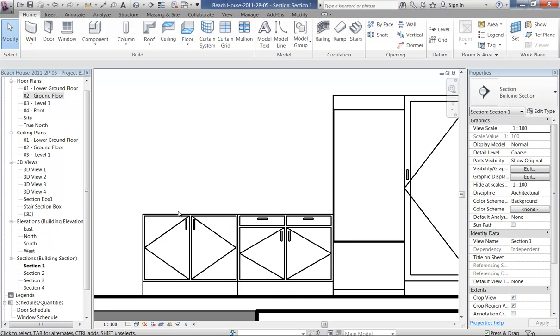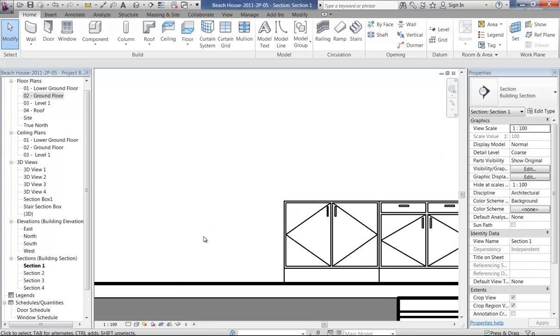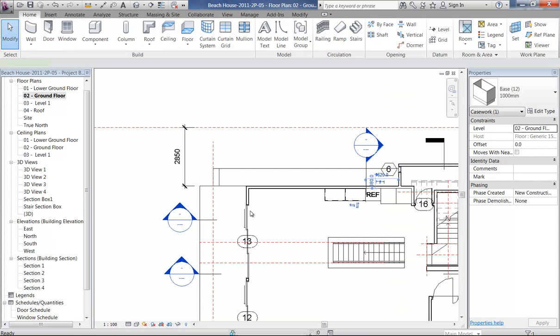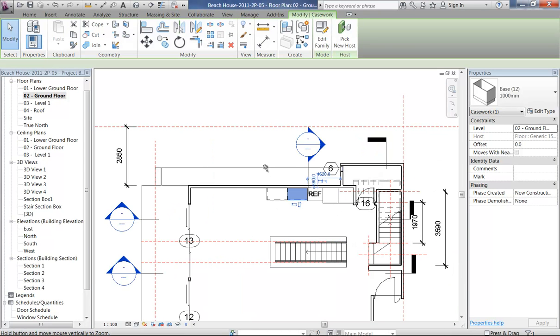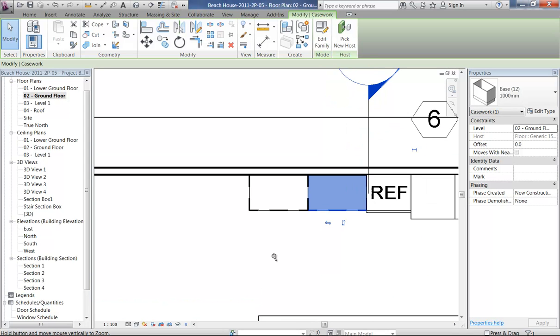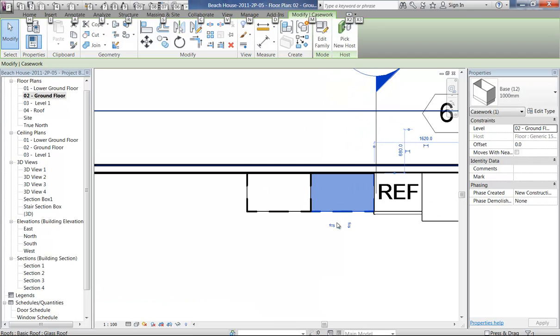That looks okay, and then maybe I'll just do one more cabinet, and I'll assume that's where what will be the stove. So I'll have the sink there, I suppose, and then the stove. Okay, so back in the ground floor plan. I'm just going to copy. So I've got that cabinet selected. I'm just going to use copy and bring that across.